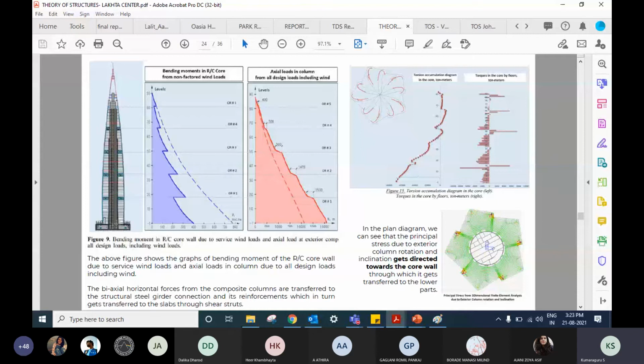Imagine if you are designing for a bending moment of this scale. Imagine the foundations, right? It needs to be fixed. The kind of forces coming there, you would put large section sizes, a lot of reinforcement bars and all that. So a simple thing like an outrigger, which is put here, of course occupies some material, but it drastically reduces the overall deflection and also causes fewer complications in the foundation design.